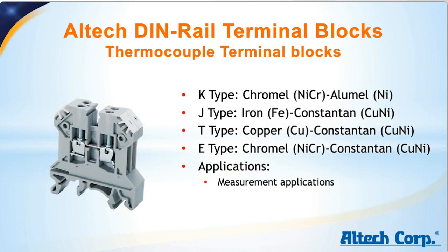So the current bars consist of different materials, because what is a thermocouple? A thermocouple usually consists of two wires or wire legs, and they are made from different metals. These legs are welded together on one end into a junction, and that is where the temperature is measured.